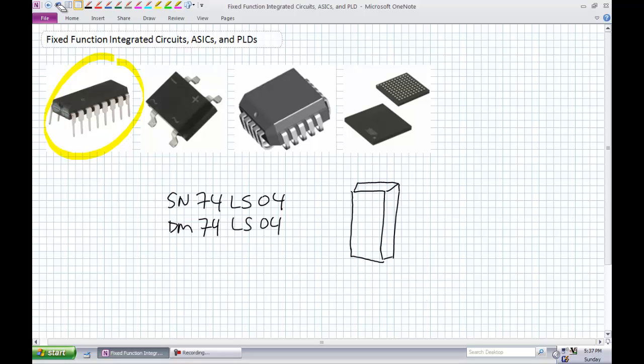Make sure it's got the correct number of pins. Make sure it doesn't have pins snipped off of it. Make sure it doesn't have any melted marks on it or burn marks on it. Make sure that the pins are not bent there, because you know who previously used that before? Maybe you. You got frustrated, it fell on the floor, you may have stomped on it, and you may have put it back in there. Long story short, good lab practices, guy.